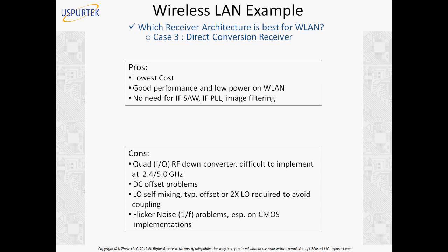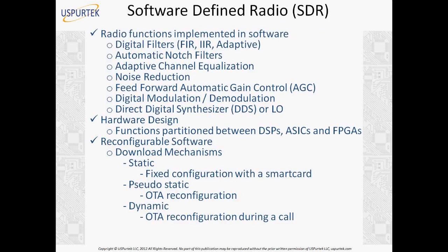If you are an electrical engineer, you always study the phase lock loop, PLL, in your college course. So what happens here? The phase lock loop is basically used to maintain a stable frequency of the oscillator. So it's a feedback mechanism. Any oscillator will generate some frequency, but how do we ensure that the frequency remains stable at, let's say, 4 gigahertz or 2 gigahertz or whatever frequency we are generating inside the receiver? So a phase lock loop is a feedback loop from the output to the input of the oscillator.